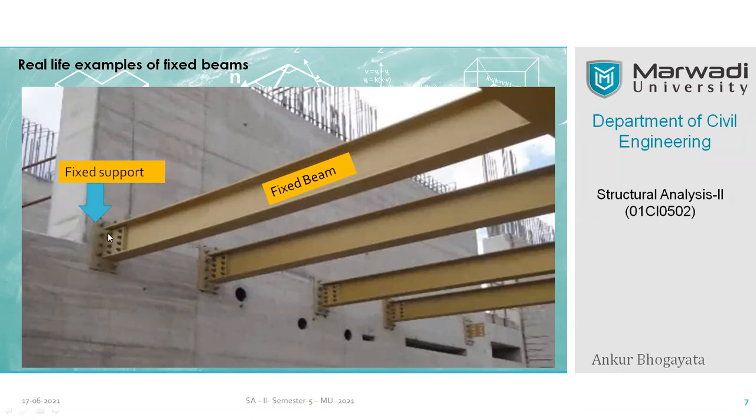Then in addition, you can have an angle, and that angle is further rigidly connected with the wall as well as with the beam, in a way that this connected plate restricts the movements at the joint for rotation and translation in vertical and horizontal direction. So that is why we can identify this joint as a fixed joint or fixed support, whatever you call it, right?